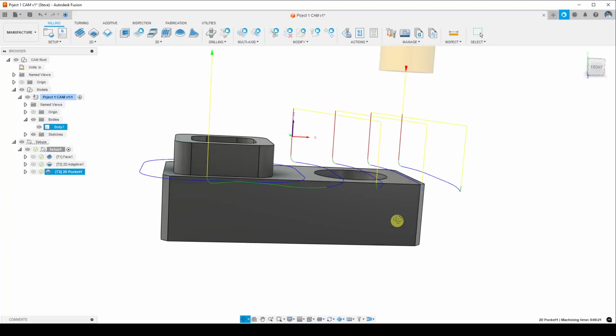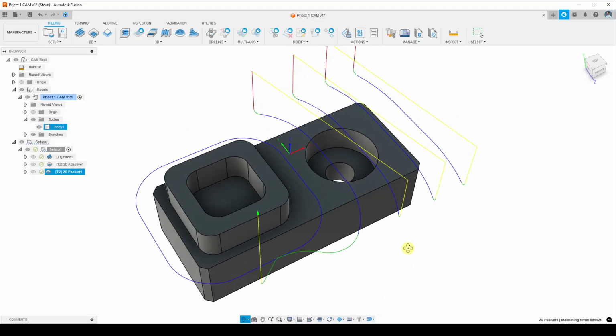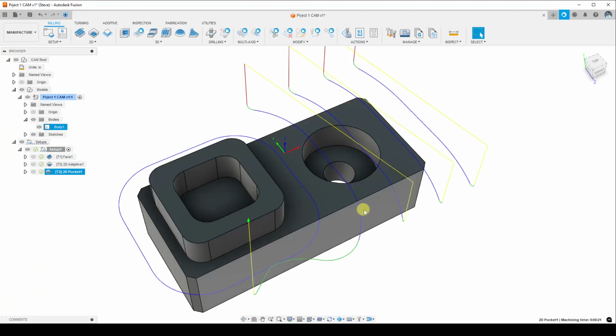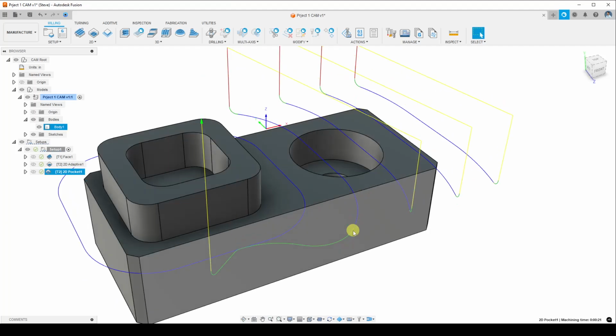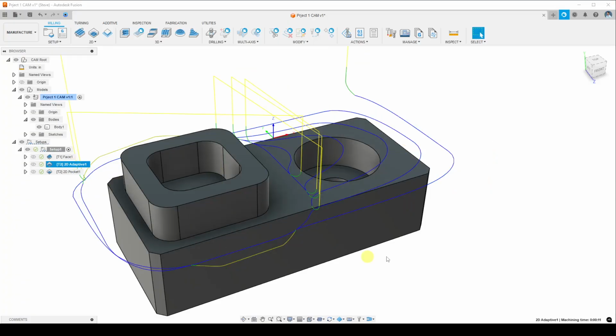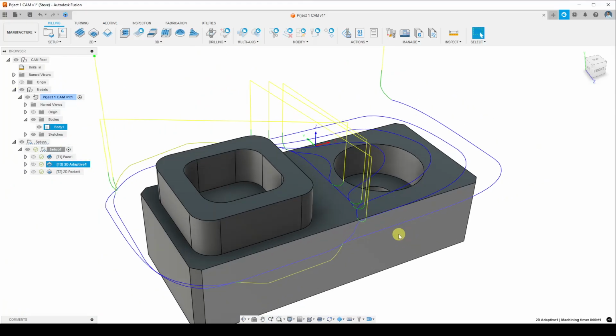You can see that that is the toolpath there to clean it up. And then the 0.3 is the distance between these lines here. I think the big difference between the pocket and the adaptive is that the pocket just uses the geometry to be machined and then the step over, and then makes that same geometry at kind of increasing size. Whereas the adaptive really considers the amount of material that the tool is engaging with.